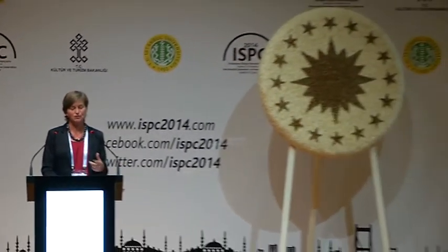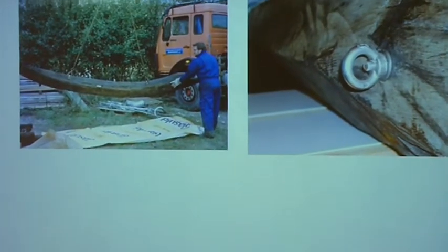It may look very drastic, but one thing to consider when dealing with very large structures is that the decision process is very long, and during these processes, these timbers will have to be lifted and moved several times. So it's a very good precaution to insert the eyebolts from the start and use them for lifting every time.